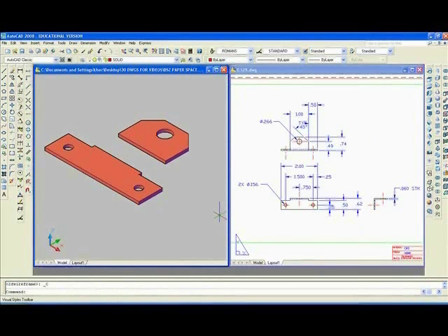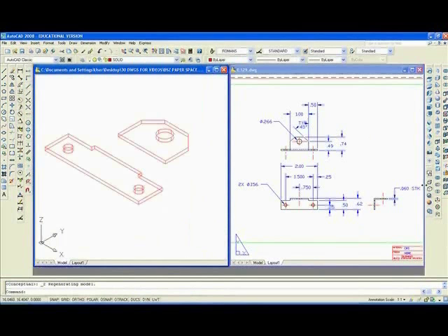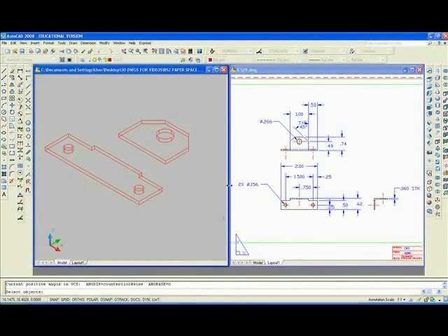It looks okay, so I'll go back to the 2D wireframe, at which point we'll go to the 3D rotate command, select that part, and put the snap on, pick a point, make the red axis active.